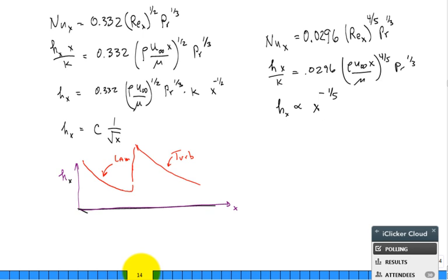So here I'm guessing they'll have correlations, and they'll say, look, we're going to do this. We're going to have an average over when it's only laminar. Great. You know what? They'll also have a set of correlations where essentially they'll just do an average over where it's turbulent. That's great. But then you say, don't we have the leading edge? Doesn't it start laminar always and then transition to turbulent? Couldn't I do an average for both laminar beginning and turbulent? Yes, you can. And guess what? Somebody else has already done it, and it's in the book.